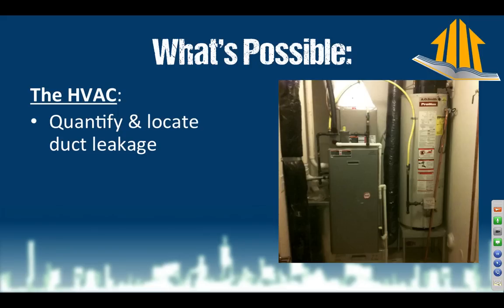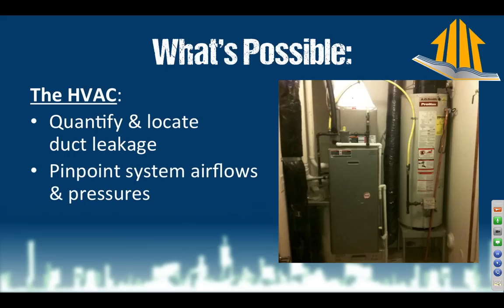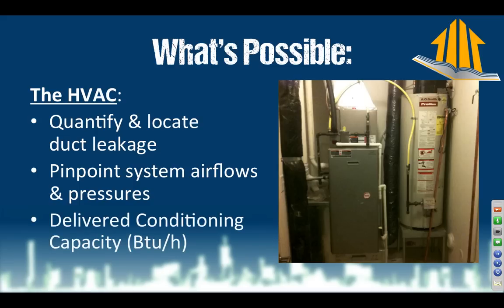You can with a duct tightness test plus theatrical fog if all of the ductwork is exposed, but you have to use a pressure pan and a blower door to locate it otherwise. You want to pinpoint system airflows and pressures, know exactly what they are before you start working on the thing and after, and you can prove that you did the thing right. And this is something that scares a lot of HVAC professionals because they don't even know that it's possible.